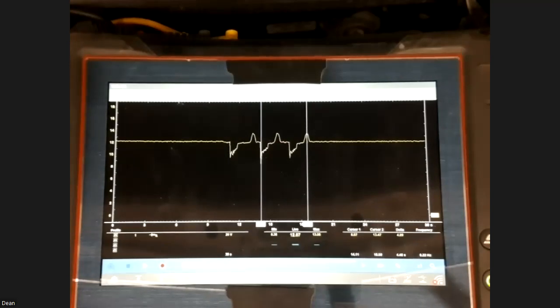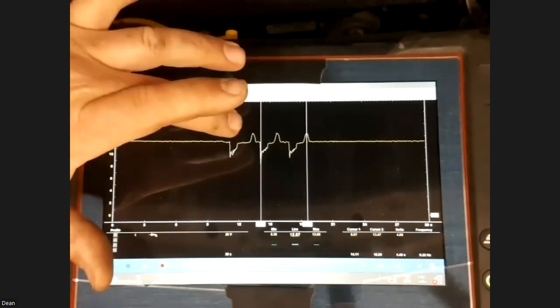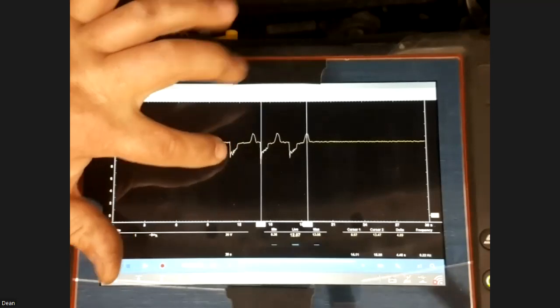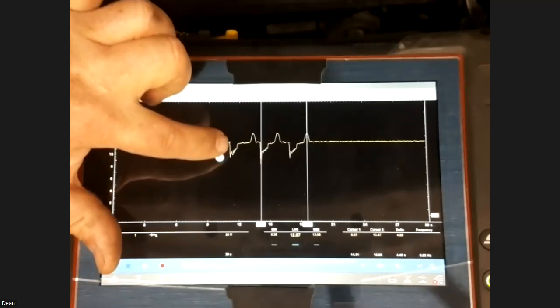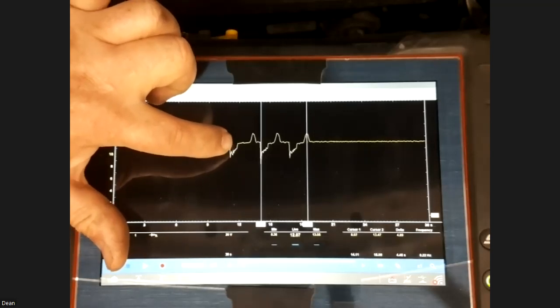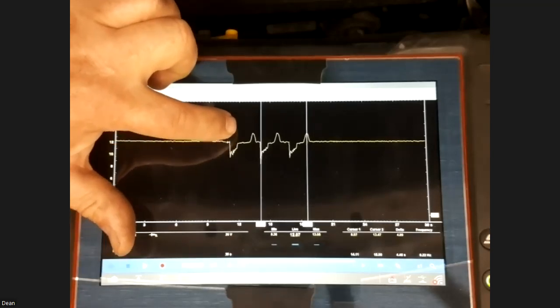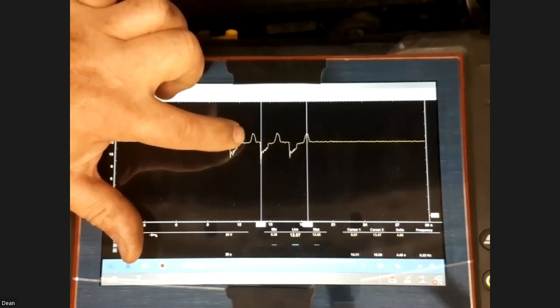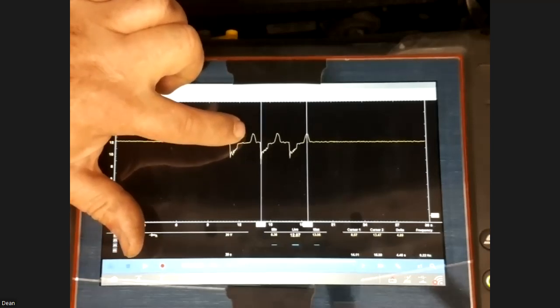8.57. That already tells me the RC of this battery is not strong enough, and it's going to start throwing codes left, right, and center. You will not get that on a digital ohm meter. On top of it, you can see right where the injectors are turning on. You can see exactly what was happening with the starter. You can see the alternator coming alive. You can see the fuel pumps and everything else, and then the alternator starts to kick in.